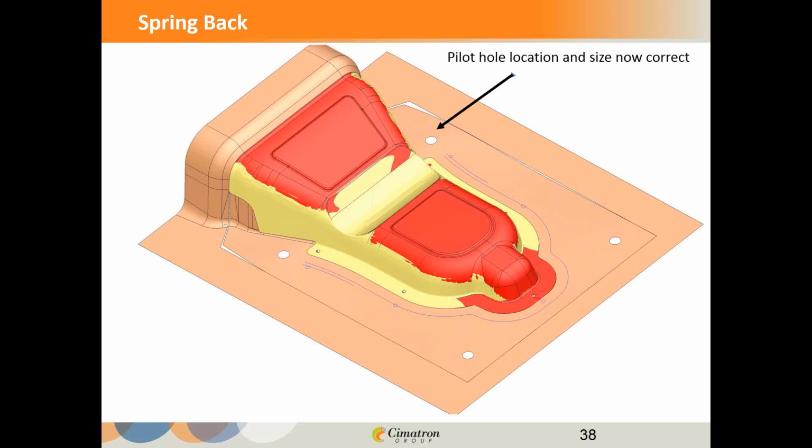We're just saying don't move the pilot holes. So there's a flexibility there where I'm not totally redesigning everything. I really need to know those pilot hole locations, and I really need to be sure they're not going to move. So that's a crucial part in understanding how the die is going to hold its form while I do this deformation.